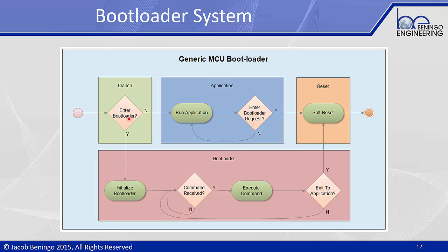So if this is normal operation, we want to run our application code, we load the application, and we just sit here and run the application code. Periodically we check to see, is there a request to enter the bootloader? If there ever is, we set that byte or whatever behavior we want, and we move through that software reset that then forces us to restart the system and come back into our branching code. The code decides, should I load the application or the bootloader? In this case, since we told it that we wanted to start the bootloader,